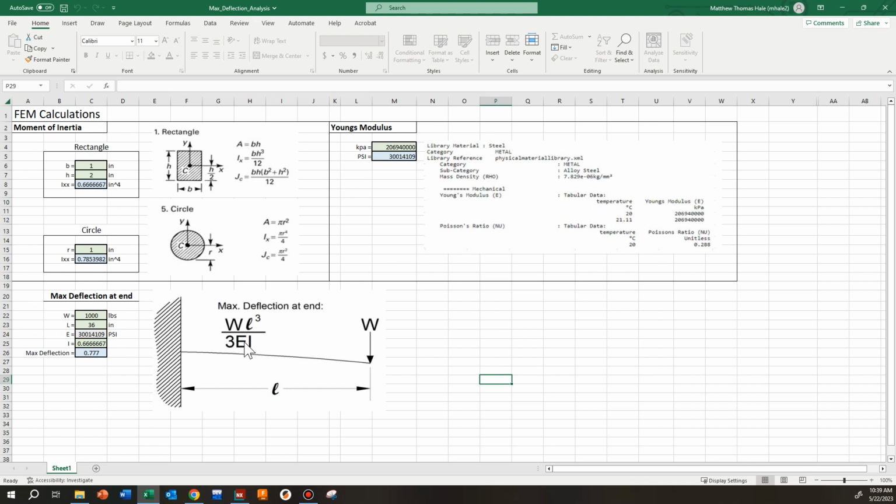E is going to be our modulus of elasticity, or Young's modulus. That has to do with the type of material that we're using. Are we using steel? Are we using aluminum, plastic? So that is going to be the type of material. And you can see up here, we're using steel. Steel generally is about 30 times 10 to the 6 psi for the modulus of elasticity.